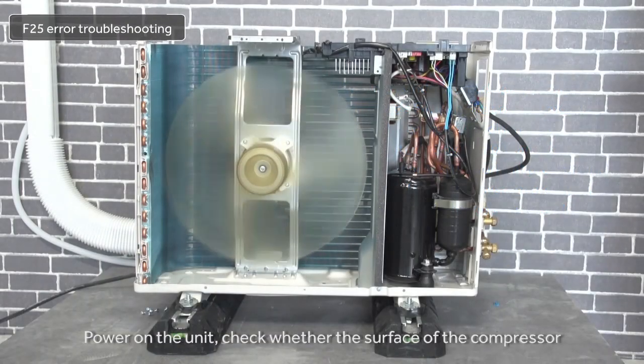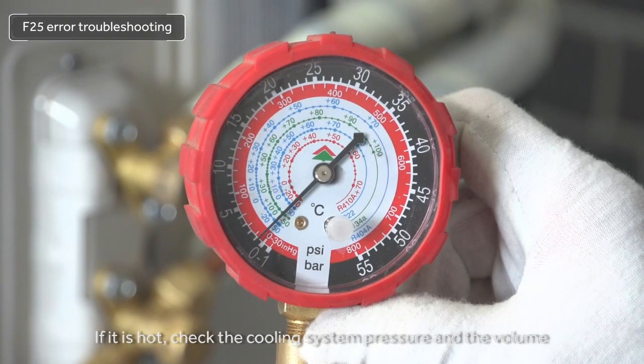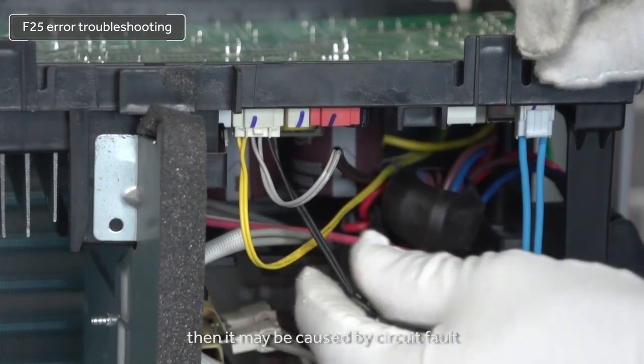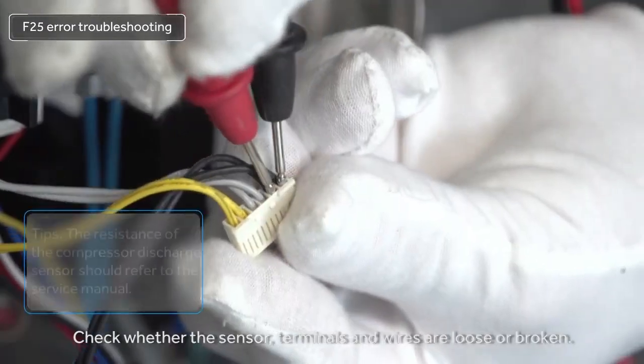Power on the unit. Check whether the surface of the compressor is hot. If it is hot, check the cooling system pressure and whether the volume of refrigerant is not enough. If the temperature of the compressor surface is normal, then it may be caused by a circuit fault. Check whether the sensor, terminals, and wires are loose or broken.